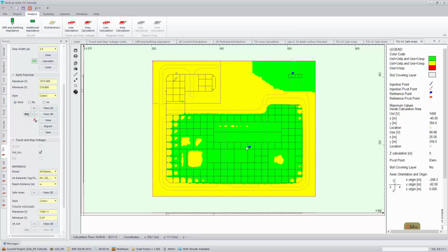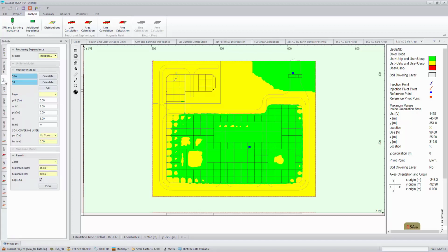Now, these reference points are very useful, especially if you have a bus bar where things are centrally grounded and the ground connection is actually farther away. You can use this as a set reference to determine touch and step voltages, or really touch voltages in that situation. What we can see is that we're still exceeding our touch voltage limits, and we can correct that or mitigate that by incorporating a surfacing layer.